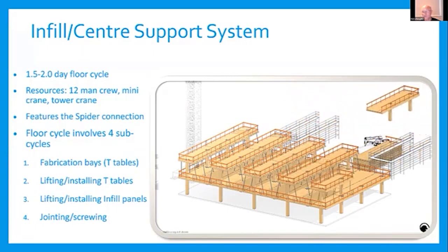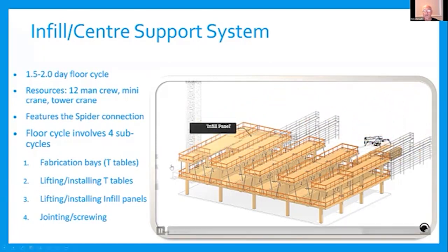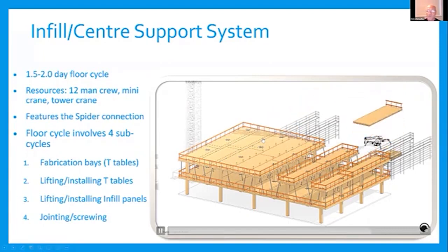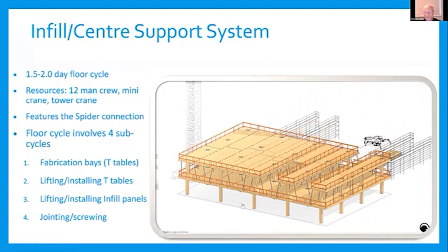removing the edge protection around each T-table. So you'll see that happen now. And the reason we want to do that is so that we can start preparing for that to be in stacks that we can then eventually crane up to the next level for the next floor cycle.